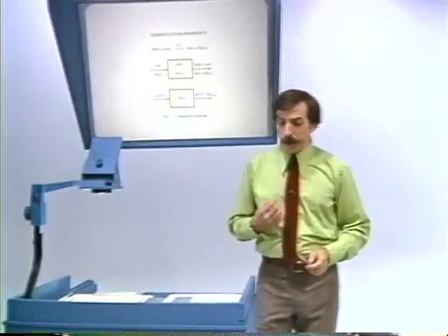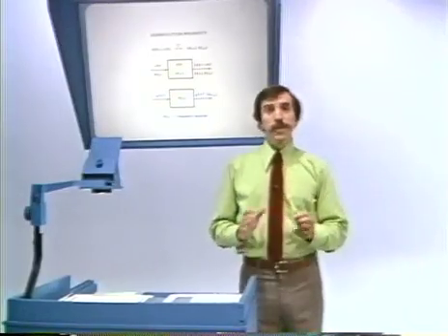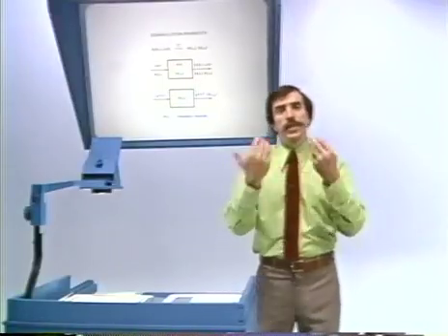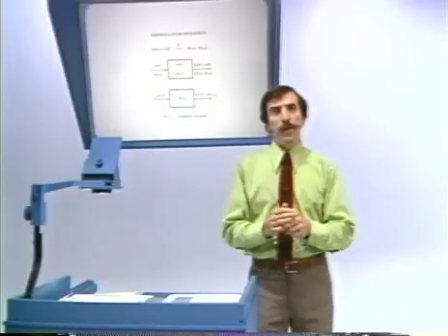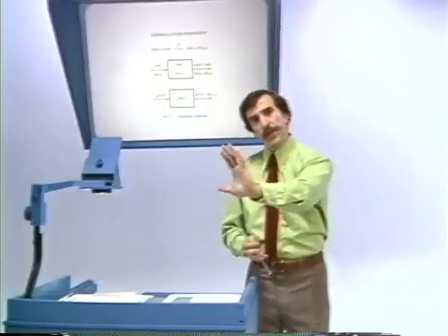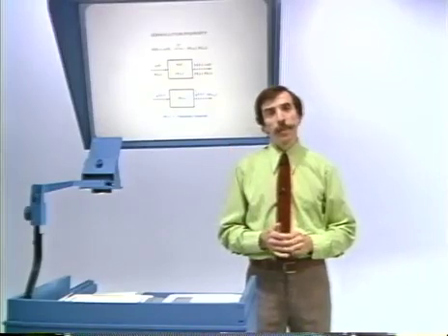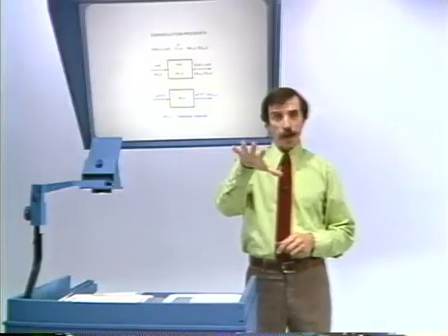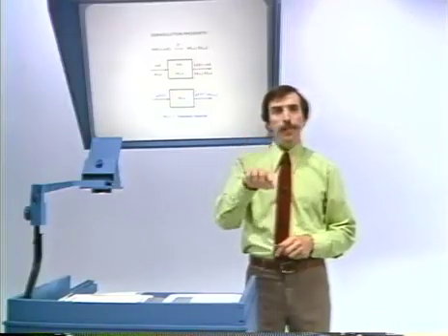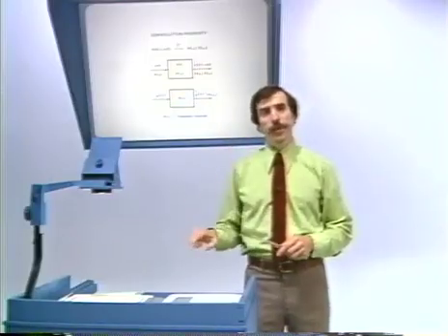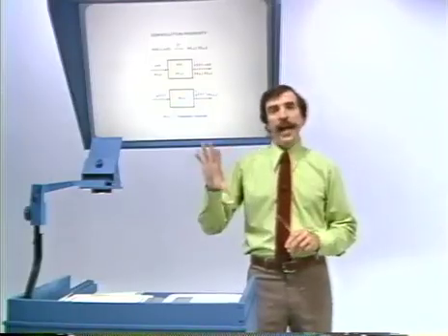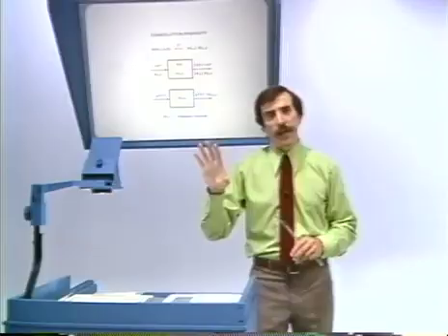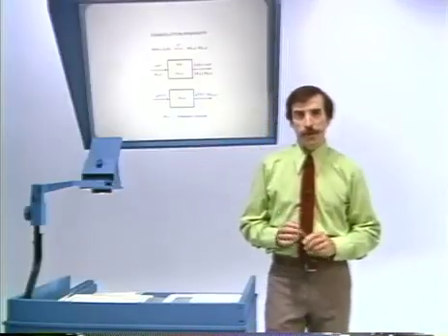So, in fact, the convolution property simply is telling us that in terms of a decomposition of the signal in terms of complex exponentials, as we push that signal through a linear time invariant system, we're separately modifying, by multiplying by the frequency response, the amplitudes of the exponential components used to build the input, and that sum in turn is the decomposition of the output in terms of complex exponentials.